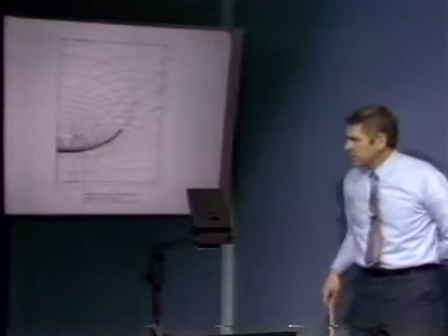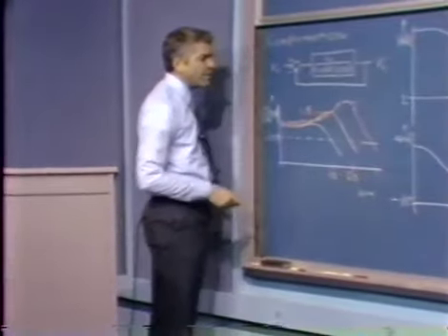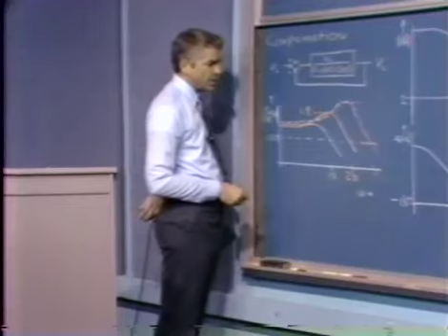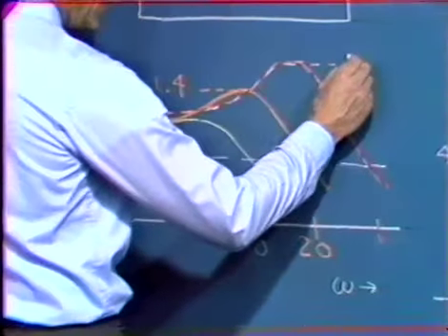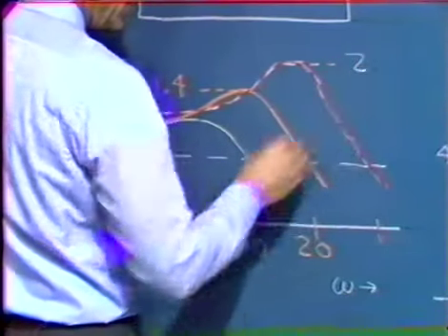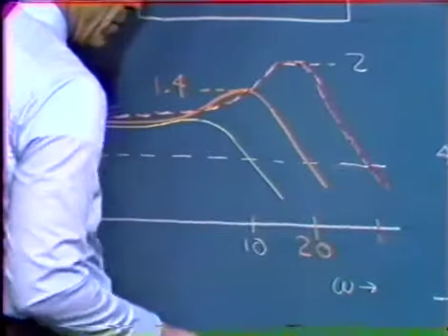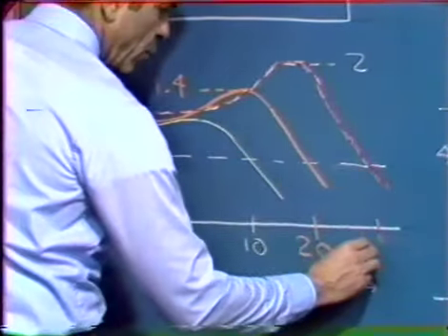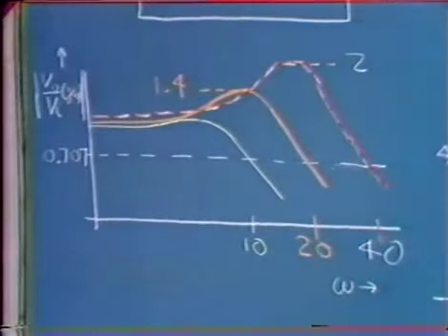And again, we can draw that construction, or determine the corresponding closed loop gain, for that value of A0, in particular an A0 of 50. We'd find that the peak magnitude is about 2, as we've seen from the Nichols chart, and that the 0.707 frequency is about 40 or 45 radians per second, somewhere in here.